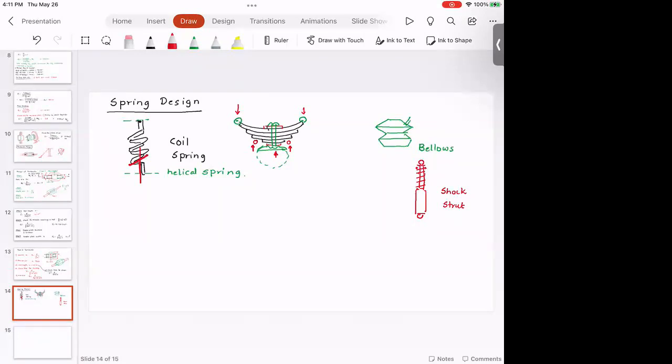Otherwise, if you just want to replace the spring, you use something called as the spring compressor, you compress the spring, you put it inside the damper, and then load the whole assembly. And that job is very dangerous, because once you load the spring, it's a tremendous amount of power, and if something breaks down, it can kill you. That's why if you want to get the suspension job done, it's better you call a professional to get a suspension job on your vehicle.